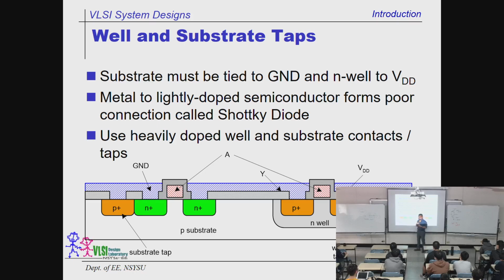So this is a problem that we have. If we apply a high voltage here, we're going to turn on the channel over here. That means that we turn on the switch. But the problem is some other areas, not in this region, might be attracted by the high voltage over here to become drifted carriers. Then these drifted electrons, they are not welcome.